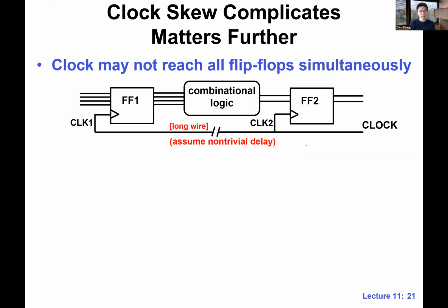I'm pretty much sure that you guys will see questions about timing analysis and clock skews in the second problem. Actually, what I heard is that when you interview for chip companies, many people ask questions about clock skews and such. So this is where we actually consider the wire delay. So far we have been assuming that there's really no wire delay. We have a global signal and the clock can reach different endpoints.